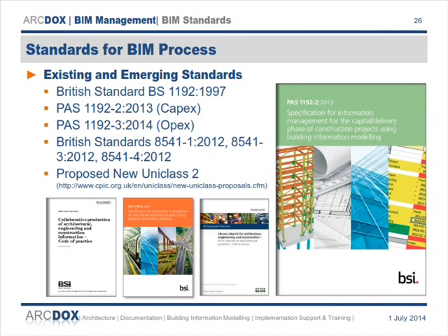They've also republished 3 parts of BS 8541, which deals with library objects for BIM. So the graphical information you need, the data information you need, how you can use those objects in models. So they're worth having as well. And PAS 1192 also requires COBie and Uniclass as the coding system. Now Uniclass went through a redrafting and is now in Uniclass 2, but it's still available as in beta format. But again, we'll look at that in a minute.